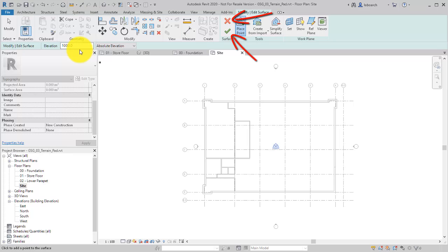You will create the Toposurface by using the Place Point tool to place points in the site plan to represent spot elevations. The Toposurface geometry is automatically generated using the points. A Toposurface can also be created from imported CAD files that include 3D contour information, or from a points file, which can be generated by certain civil design applications.